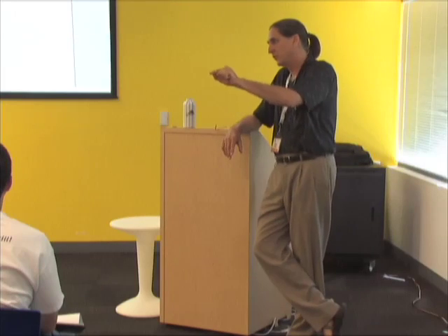When I use the zoom window command, it doesn't always give me what I'm zooming. Yeah, zoom window will go to the context of whatever it perceives you're trying to go to. So again, if you try to use wireframe and limit it, the real power of SketchUp for me is all the inferences, but those inferences really kill you when you're zooming in, because it's doing the same thing. It's going, what of these 1,000 points that you just put your window over do you really want to go to?